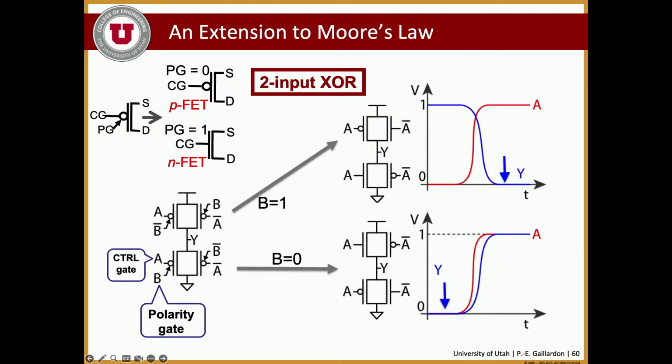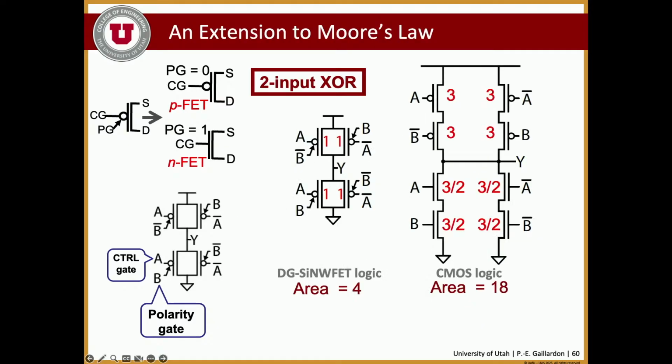And that has to be contrasted with what you would get with a CMOS logic implementation. In CMOS logic, you would have 8 transistors to implement the same functionality. These transistors have to be sized differently because these N-type and P-type devices do have different conductions, and so you need to account for that.